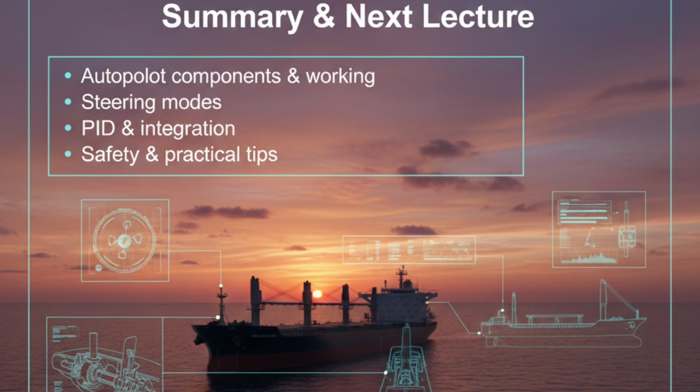As we come to the end of this lecture, let's quickly summarize what we have learned today about the autopilot system and steering control modes. In this session, we understood how the autopilot system integrates with the hydraulic steering gear to maintain a ship's course automatically and accurately. We discussed the role of the gyro compass in providing real-time heading data and how that information is processed by the autopilot controller.